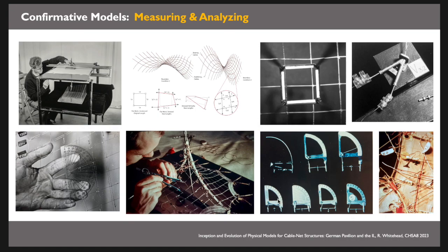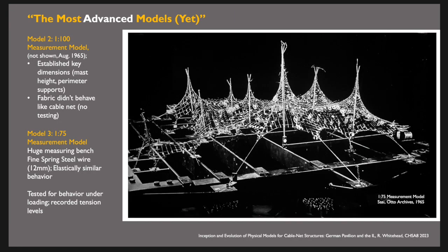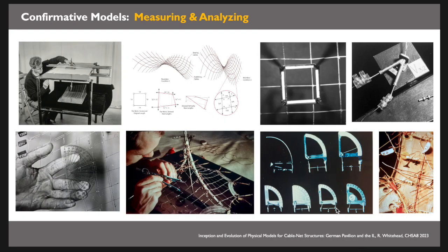They also invented a tension gauge. So this tension gauge that they had, you could actually apply it to the model. I think if we go back, you might be able to see these tension cables in there. You can see how they're incorporated all throughout there. And what those tension cables do is it's got a little meter on it, and it shows how much tension, because it's secured on the two ends, and another piece that loops around the back. And so if that's pulled in tension, it pulls the meter up. So in that, you could then, again, tune this thing and say, we know how much tension is on this wire versus that one versus that one.